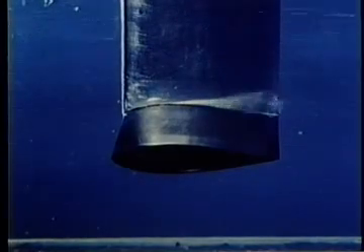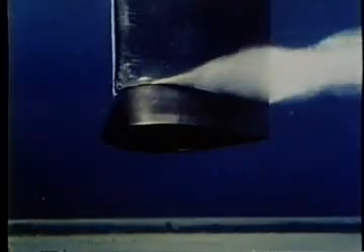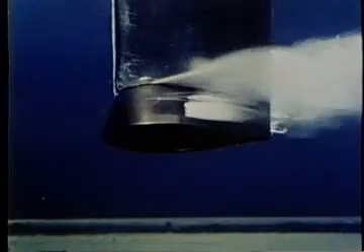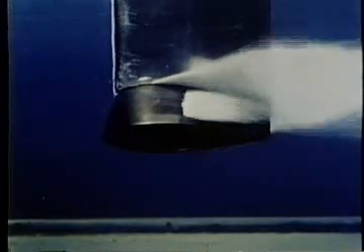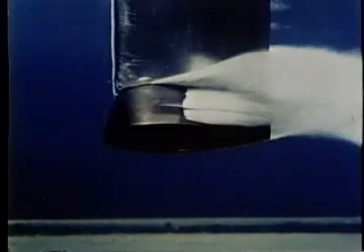Cavitation occurs first at the intersection of the hydrofoil and the strut. This happens because the presence of the strut causes a greater pressure reduction at this intersection than elsewhere on the foil. But we will confine our attention to the foil section away from the influence of the strut. At low speed, cavitation on the foil itself first occurs in the low-pressure core of the laminar boundary layer separation region associated with low Reynolds number.